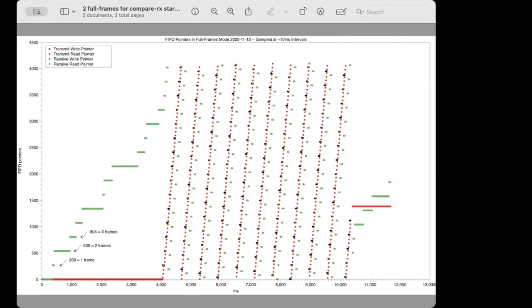And what you also see on either end of the graph here is the receiver randomly picking up what it thinks are frames. So over here on the left-hand side, you see a frame coming around time equals maybe 250 or 300 milliseconds, but there's not really a frame there, so it just sits there.